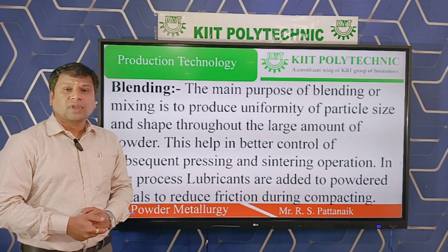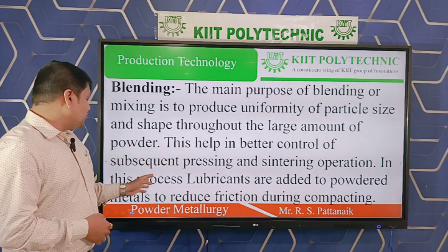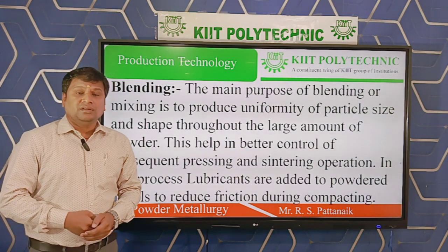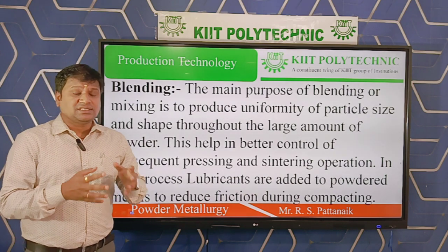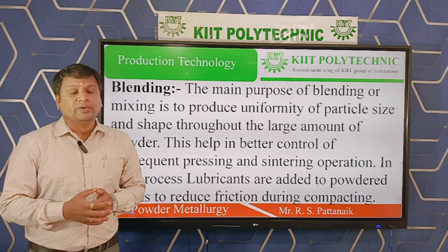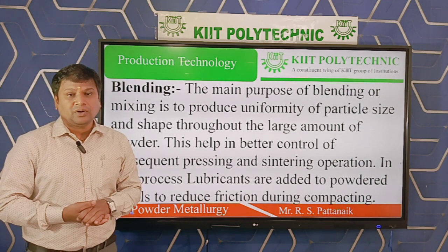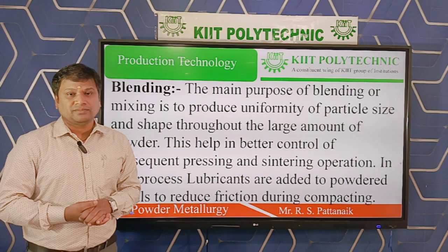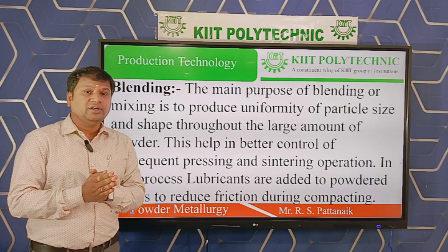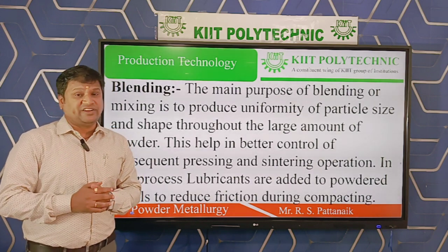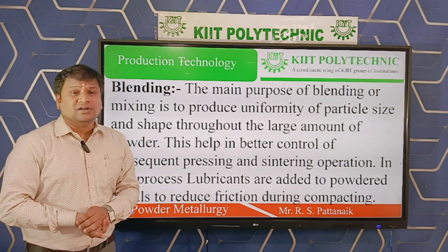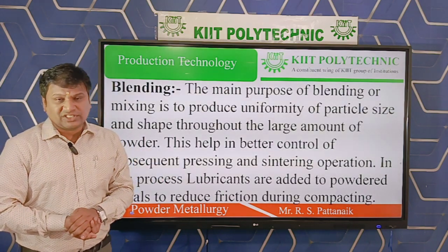This helps in better control of subsequent pressing and sintering operation. There is another thing. In this step, lubricants are added to reduce friction during compacting or compression of metal powder. So this step is known as blending or mixing.